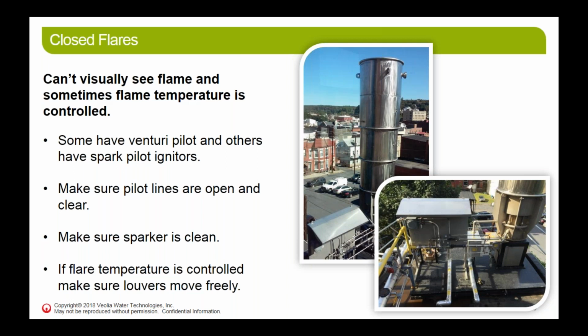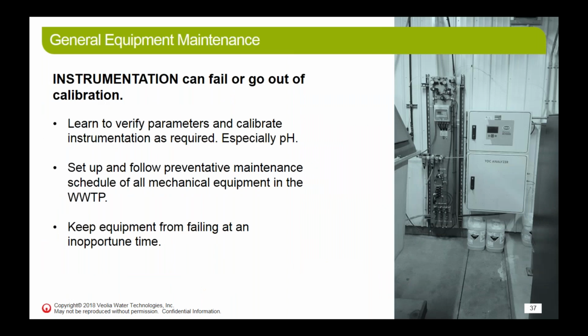You can control the temperature of the burn in most of these closed flares, and that makes them cleaner. So some of the states that have a lot of clean air regulations usually require an enclosed flare so that they can regulate the temperature. And if you have the temperature control, it's usually done with louvers, so you have to make sure that the louvers are always maintained and free moving.